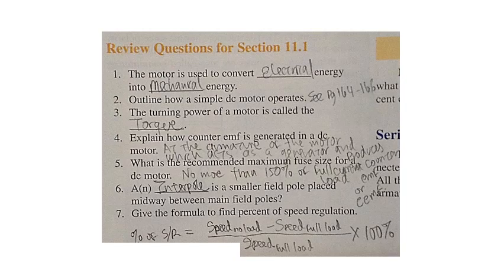And this voltage of opposite polarity will go against, or will fight, or will oppose the voltage that you are feeding in to the field windings through the battery, and it will more or less resist this voltage since it's of opposite polarity, thus being called counter electromotive force, and will act as a resistance to the motor.